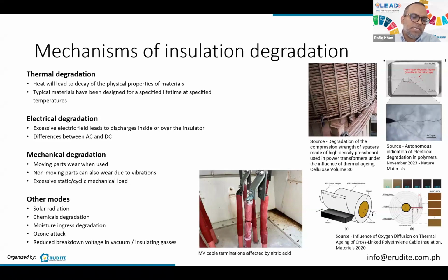PVC, HDPE, or other materials which are exposed to the sun begin to crack. Solutions for it sometimes are graphite coatings, which cover these primary plastic parts. Graphite is a bit more inert and doesn't react with the solar radiation so fast, and it gives a bit of a lifetime.